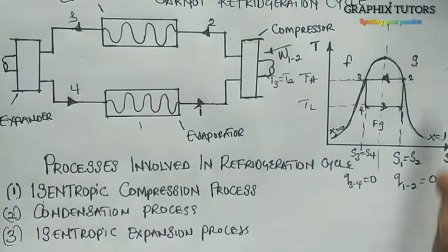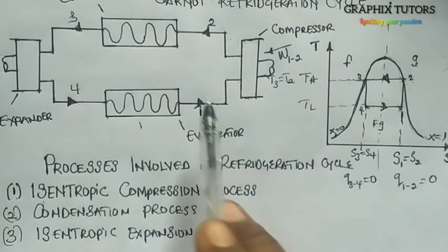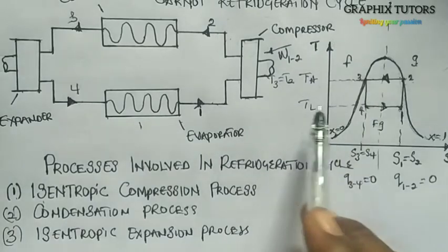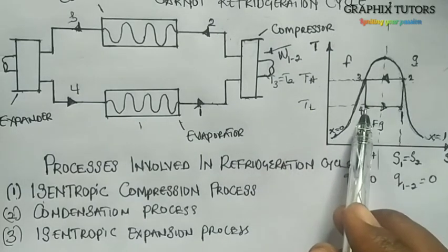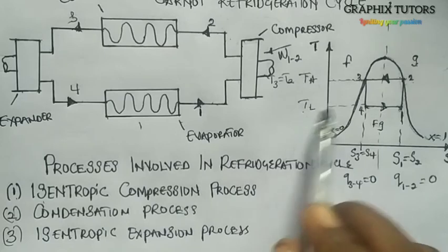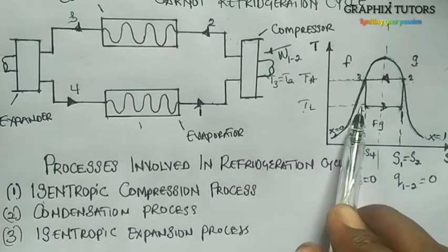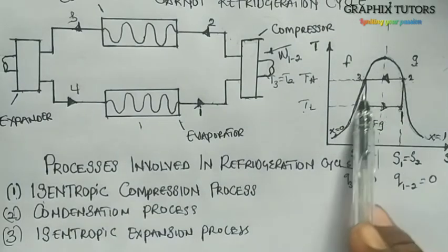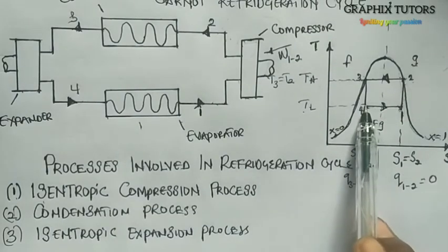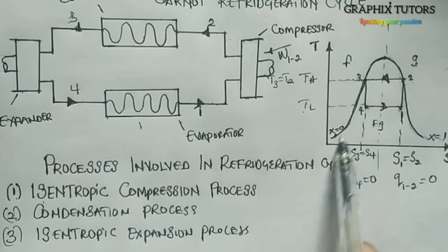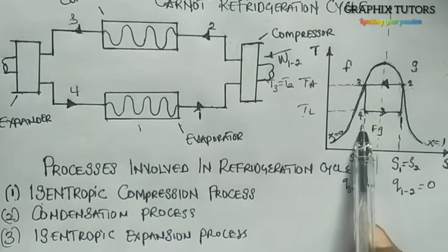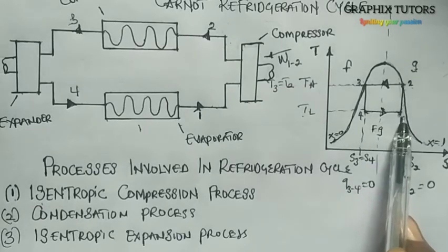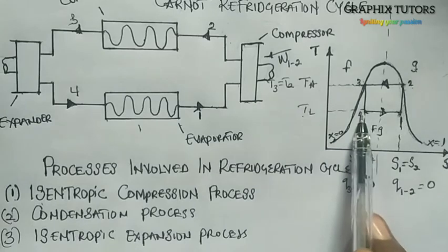Now it will move back to its original low pressure. Initially at state 1 the pressure is low. Here also pressure will be low and temperature also will be low, because if you look at this graph here, T4 is low. So it moves from high temperature to low temperature. Right? It still falls in between here, but it's closer to this dome like shape. So it means that as it's closer to this point, we have more liquid than gas. Here we have more gas than liquid. We have more liquid than gas at state 4.